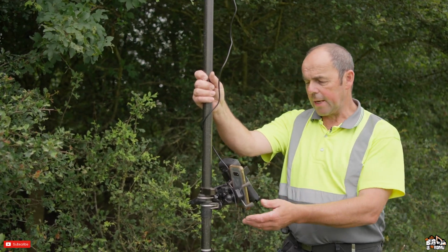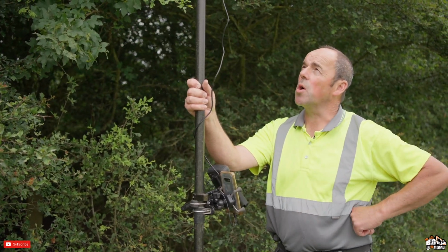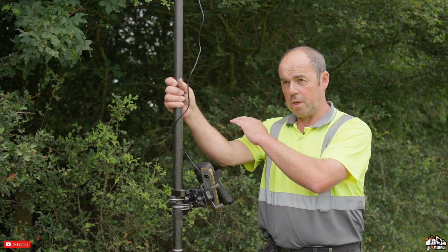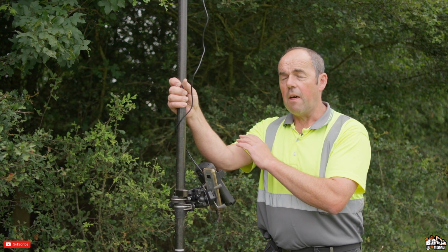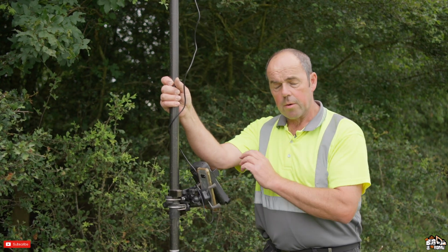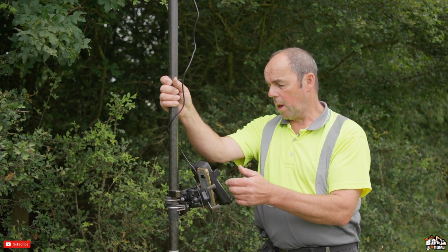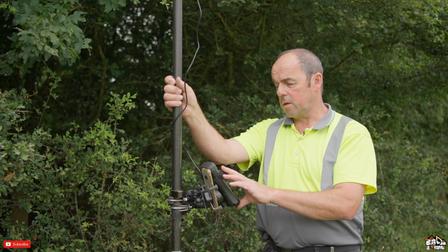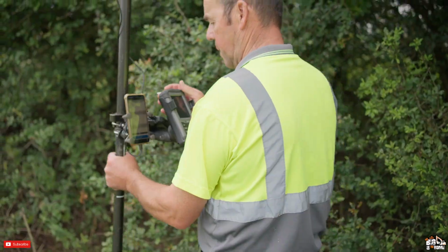Lee's already explained a little bit about it. Basically, we're using satellites to this receiver on the top here, but we've also got the base station set up on the offices. We're just using it as a standalone base station, collecting data continually, and then that's sending a signal through the Wi-Fi to my phone, and then I'm recording data on my phone. I'm also recording some data on this data logger as well. Sometimes it's just easier to put in more detail on the data logger than just the phone only.